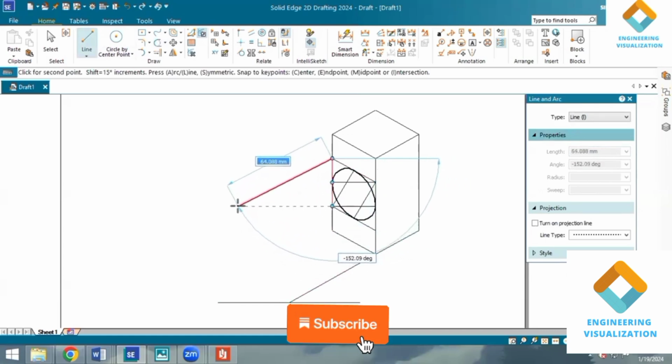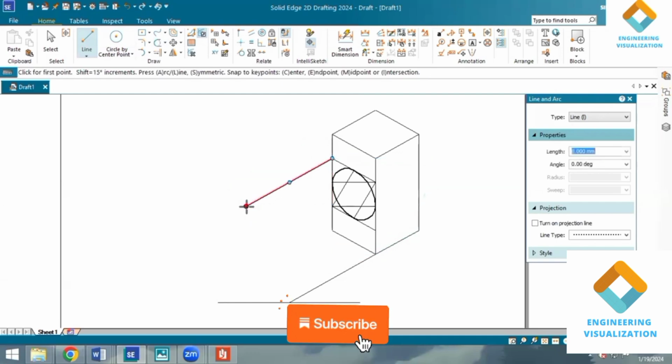So length of 60, angle minus 150. Because we should be extruding at a distance of 60 mm, right? That's why I'm considering this length of 60, angle minus 150.